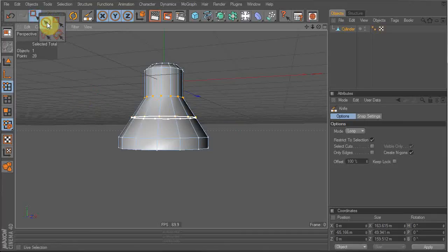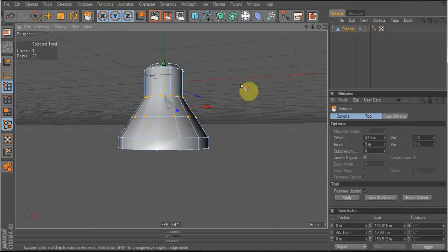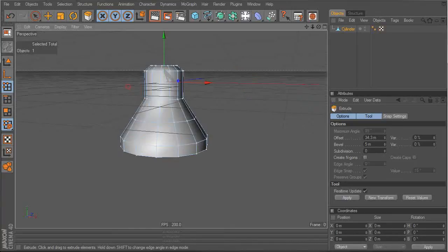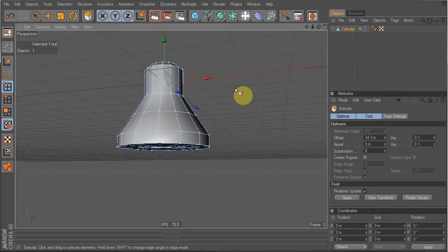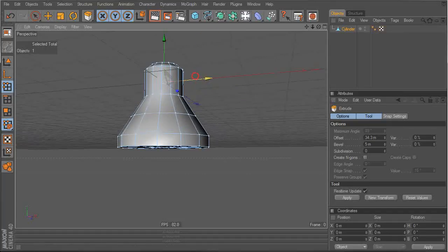See, you just wait. Let's change tools to like D. Now holding the 0 key. Yeah, see, you hold the 0 key on your keyboard, and you can draw the selection without switching tools. Very useful. Obviously, map that to whatever you want. I'd probably map that to something close to the left side of the keyboard, but it's up to you.